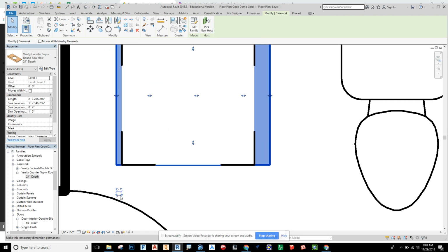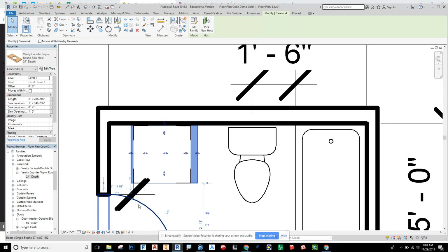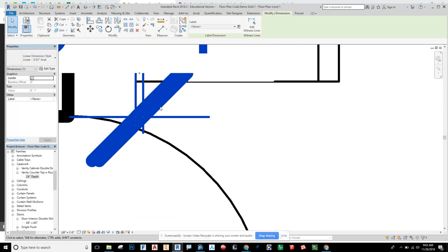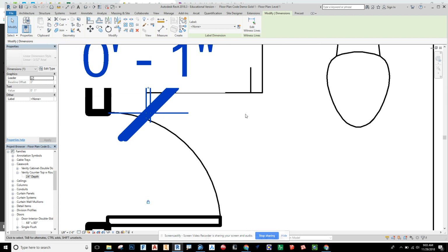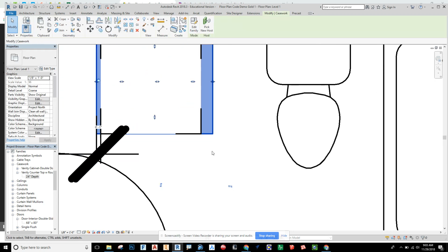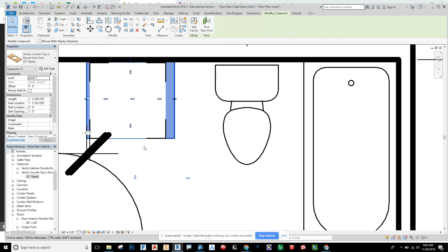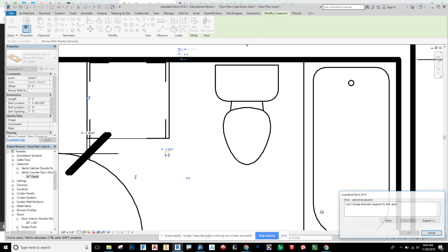Oh, we might have to lock that in real quick. So why don't we do that? I clicked on the dimension button. And where's the lock? There it is. And let's try and dimension this one over here. And it's giving me some issues here. When I drag that in, there, I made it equal. Kind of new to reference it that way, but now I can click, drag and reference. There we go. 1 inch, remove constraints.